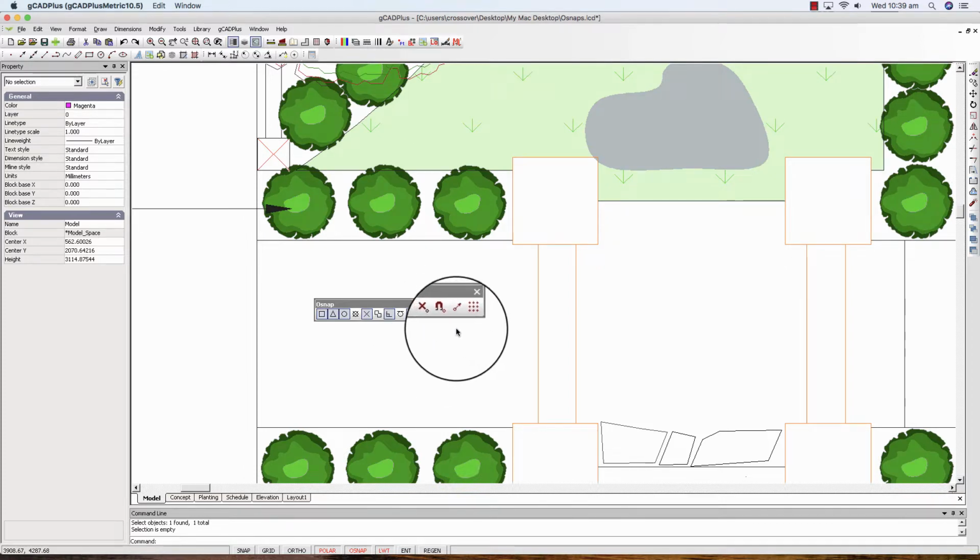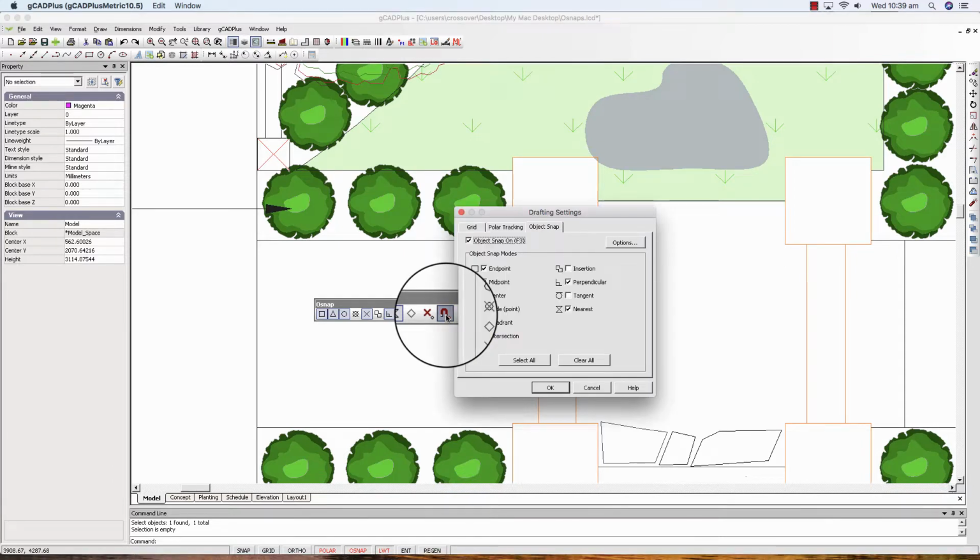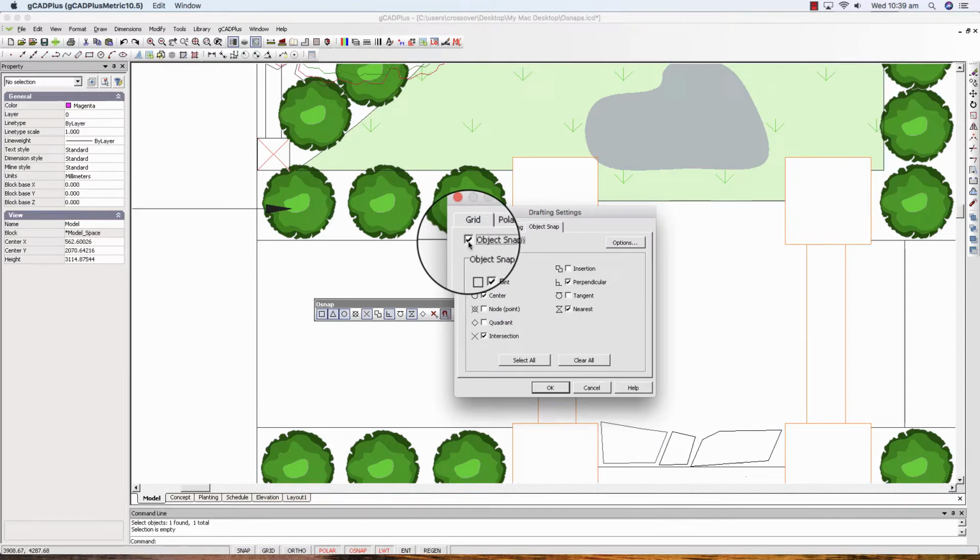If we go across to Object Snap Settings, this particular dialog box pops up, and you can see that all the tick marks are alongside the Osnaps that I've mentioned, but critically Object Snap is running and on, and I draw your attention to the F3 key.